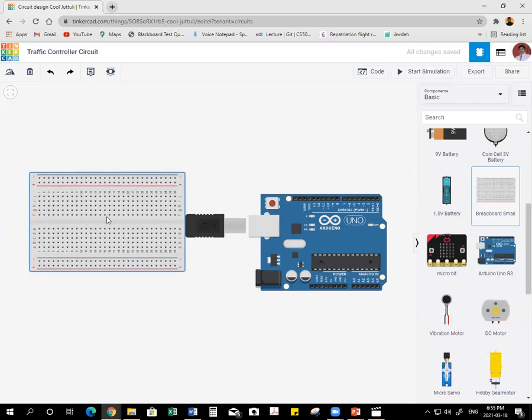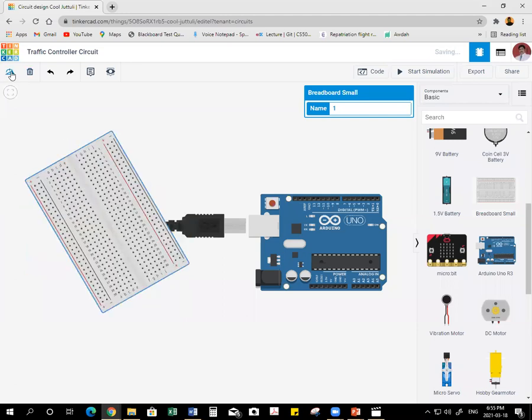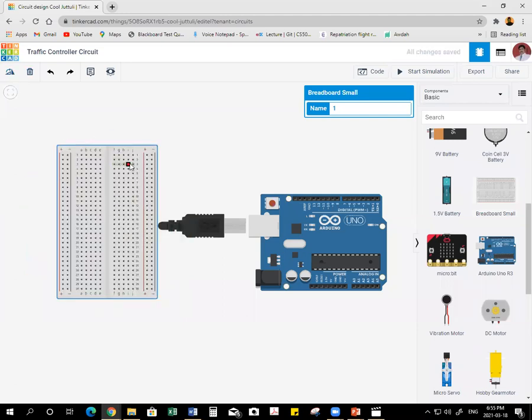So you can use the breadboard and you can rotate this. How the breadboard functions, I will show here. See here in the breadboard, plus and minus terminal names are there. If you place the cursor on the first point, it shows all the green circles, which means internally from the back side they are shorted, all internally connected as one. If you use this as one pin, all are the same pin. Similarly, this is the second one for minus.